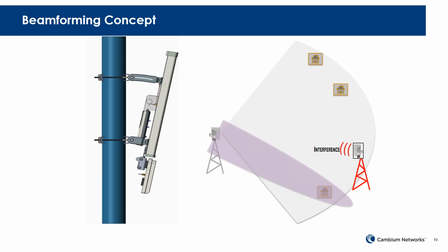Now, the really exciting thing about beamforming is that it's not limited to just 2 receivers like ears on our head. We only have 2 ears, and so in our example, we're only ever going to be able to combine 2 signals. But with radios, we can implement a radio design with maybe 4 receivers or 16 or 256. And as you add more and more transceivers, you do 2 things. You, again, increase the gain of your intended direction that you're beaming towards, and you also decrease the signal of any interferers outside of that beam.